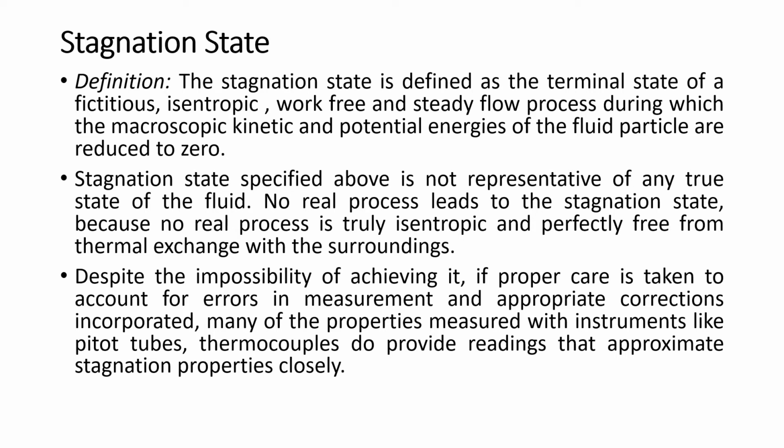Now let us understand the definition of stagnation state. The definition goes like this: stagnation state is defined as the terminal state of a fictitious isentropic, work free and steady flow process, during which the macroscopic kinetic and potential energies of the fluid particle are reduced to zero.